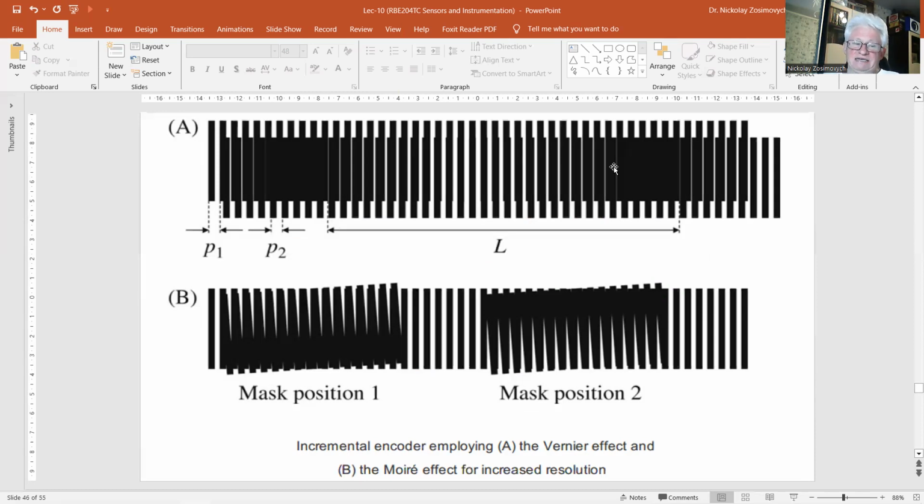Light is conducted to and from the grating through a pair of optical fibers, transmitter and receiver, providing the measurement of the transmission, which is modulated by movement of the mass. Due to the small angle, even small displacements of the mass result in a measurable displacement of the Moiré pattern.